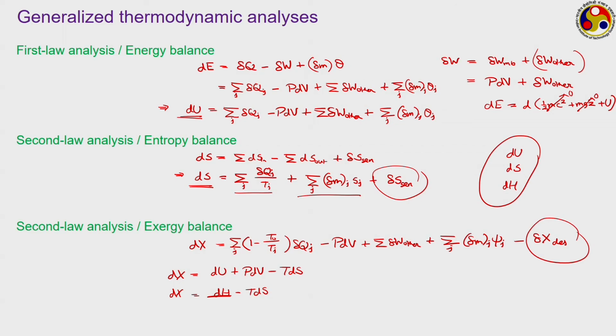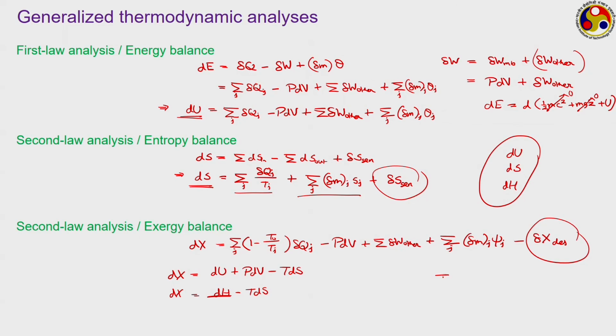So, in common thermodynamics we can classify properties in two different manners. Of course, one type of classification is intensive and extensive, but here we are talking about the practical sense. A group of parameters like temperature, pressure, specific volume, mass, etc. can be measured very easily, whereas parameters like internal energy, enthalpy, entropy, etc. can't be measured directly.